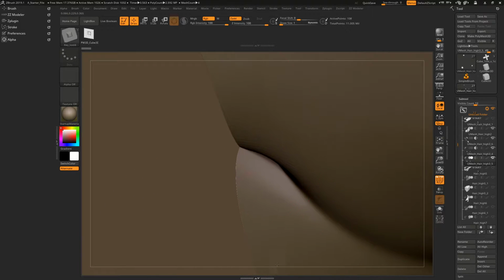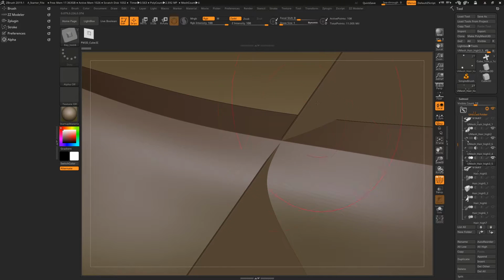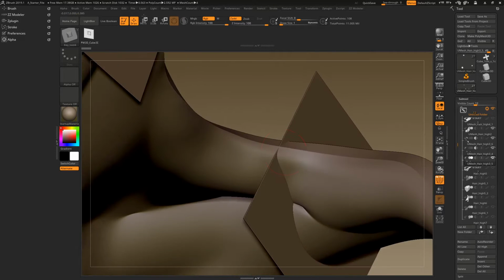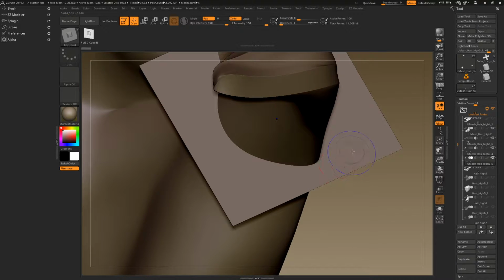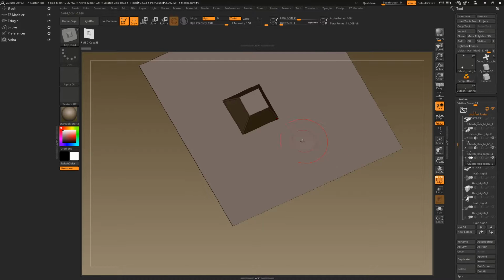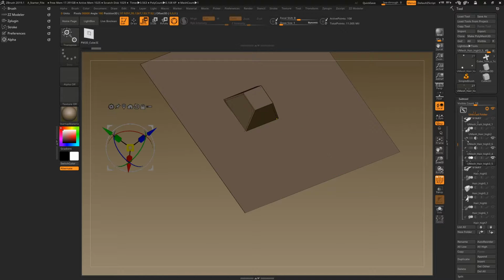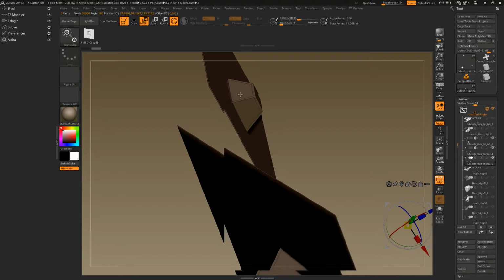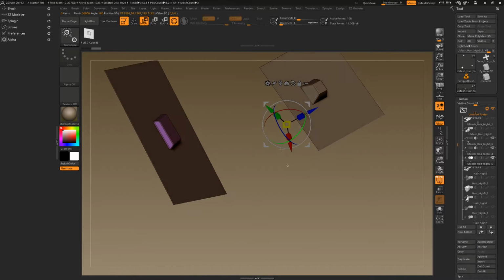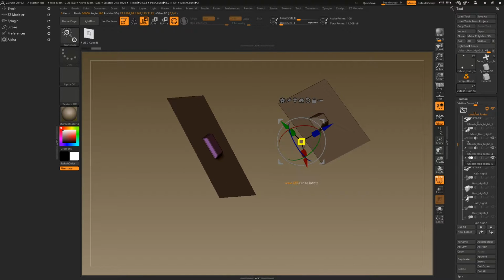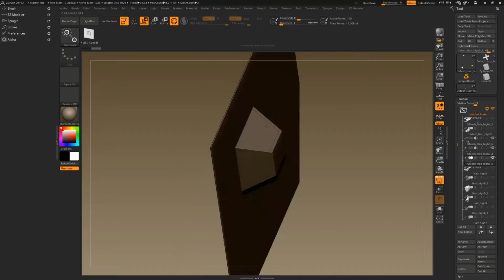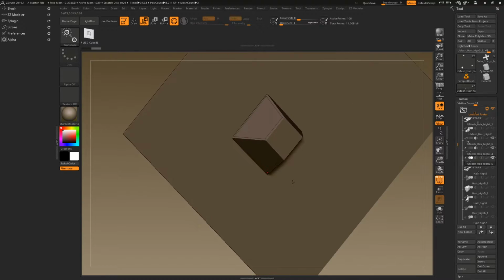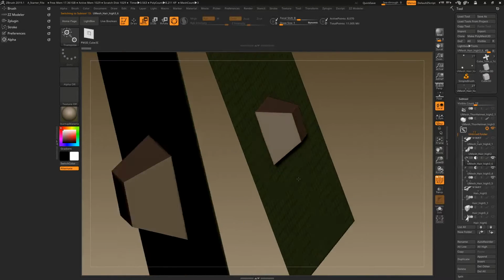This is the thing that always gets people in trouble: not double checking their cut planes. These cut planes need to be lined up just so. If you grab a plane, see, this one seems to have been nudged somewhere along the line. I might resituate that one. I'm just going back through and double checking where everything is. This one must have gotten bumped somewhere.